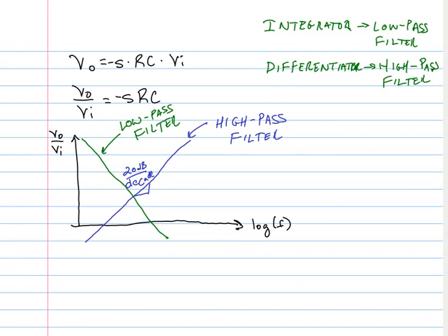Relating this to your mathematical classes, when you do an integral, it is essentially doing an averaging operation, and averaging operations are low-pass filters. And your differentiator is finding the slope of the function that you're inputting to it. So when you take a derivative, you're providing a high-pass filter. We'll build the circuit tomorrow and measure its performance and see what the high-pass filter does to an audio signal.